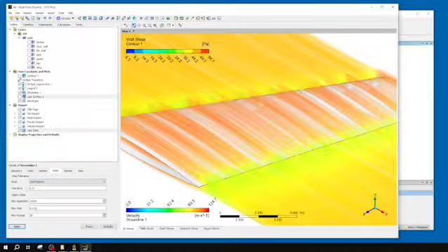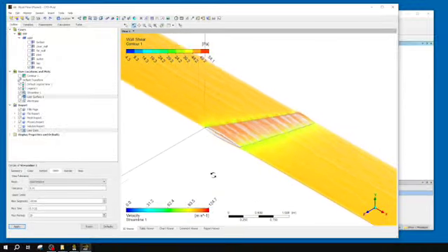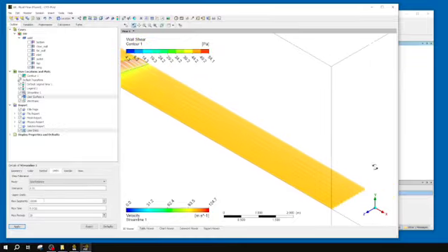Your limits, I'd suggest not playing with these too much. Basically, by changing my max segments, you can kind of start to cut off the end. So let's say I only wanted streamlines to end about here. I might decrease my max segments. It's very finicky, to be honest. And one of the things it does consider is the flow speed.